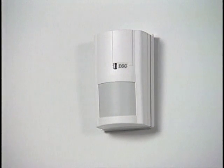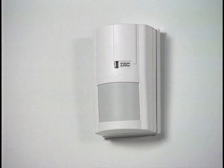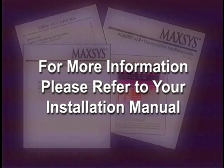The LED on the motion detector and glass break will not come on during normal operation. To test the motion detector coverage pattern, tamper the unit. To test the glass break detector, tamper the unit by pressing the button on the side at the bottom of the base.